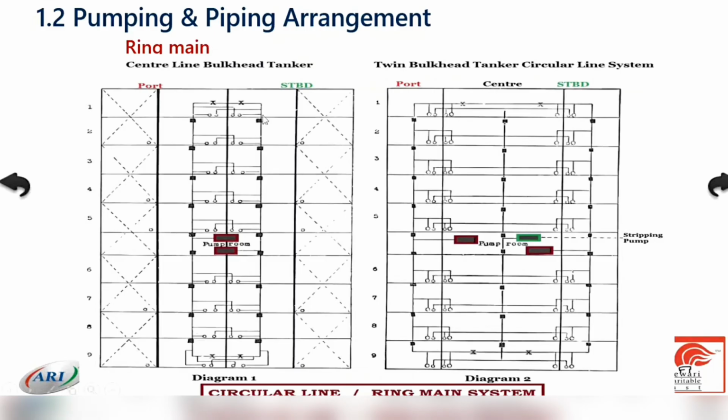Putting the oil on the starboard side of the pipeline, one port, I'm talking about one port only, and the rest are all the same. It has two different bell mouths in each tank. The ship is divided into ballast tanks on the extreme starboard side and extreme port side, and the center part is divided with a centerline longitudinal bulkhead into port and starboard tanks.